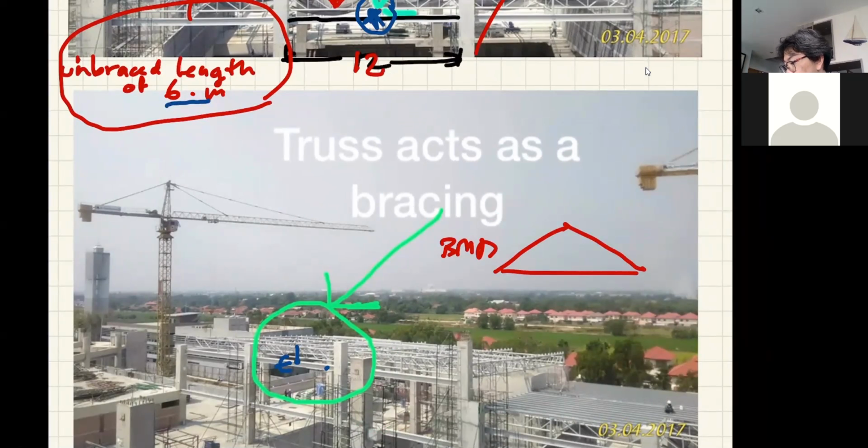And my unbraced length is also here as well. So my unbraced length, or LB, is 6. And then I will also consider the fact that my bending moment diagram is not constant. I consider both of that. That's why the beam doesn't look so big at all.